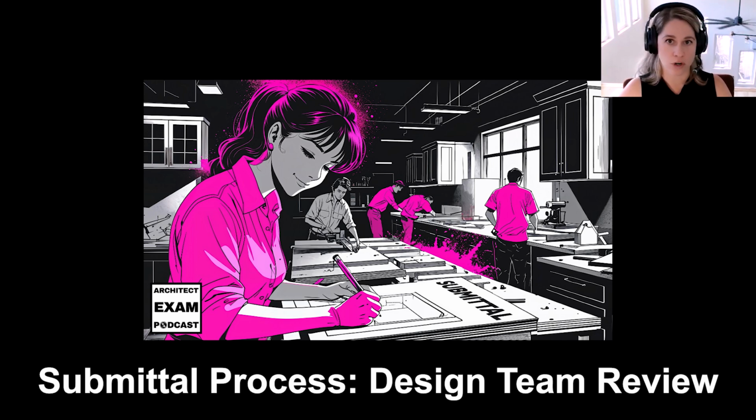So this is very important to understand for the ARE exam, the CDT exam, and just in practice. Architects are checking for conformance in submittals, that it matches the design intent, but they are not taking responsibility for dimensions, quantities, or the correctness of this submittal. That is the general contractor's responsibility.